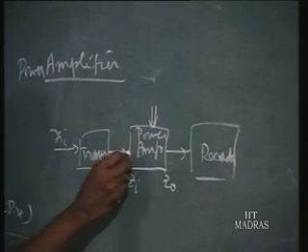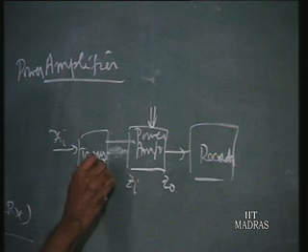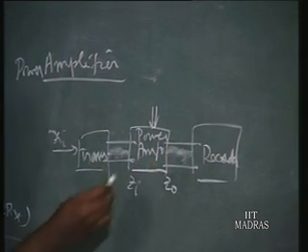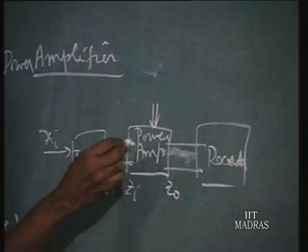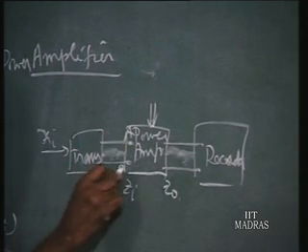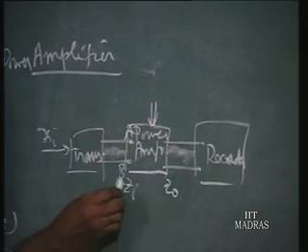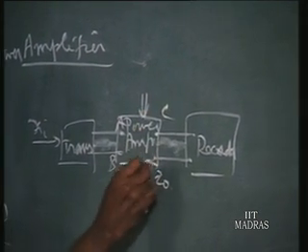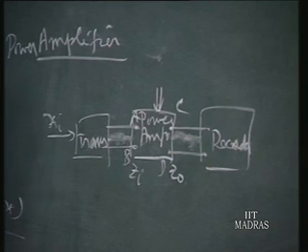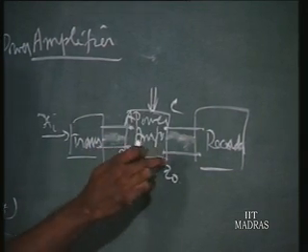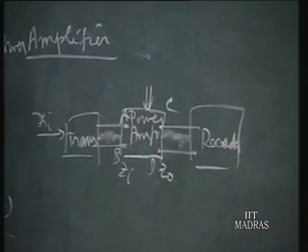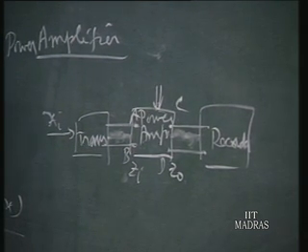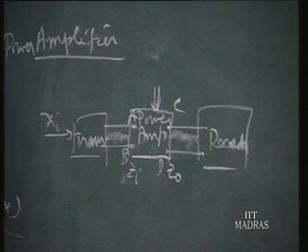At the same time, for the transducer I consider two terminals. Here also I consider two terminals, which is the actual case. So when the amplifier is seen across the terminals A and B, the circuit should possess a large value, that is ZI should be very large. And similarly, if I consider the two points C and D, the output points of the amplifier, when the amplifier circuit is seen from C and D, it should possess a smaller value, or ZO should be small, and here ZI should be very large. This is the characteristic that is required, that inherently is there in the amplifier circuit.